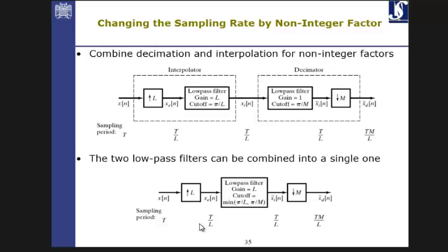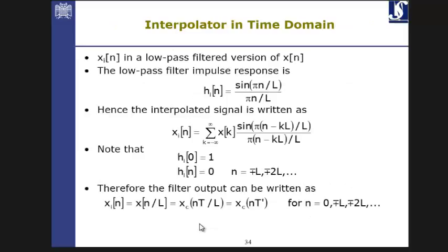So that's what you do when you actually do upsampling: you interpolate the data in between, right? That's just an interpolation, and the interpolation is actually done using the sinc function. So that's a difference between the linear interpolator and the upsampling interpolator. The linear interpolator is actually just putting, for example, if you have one sample here and one sample here,